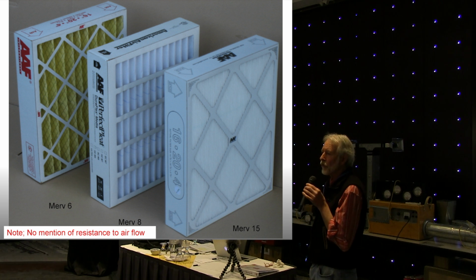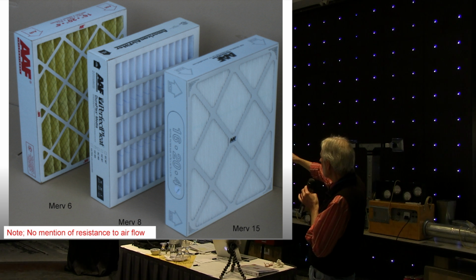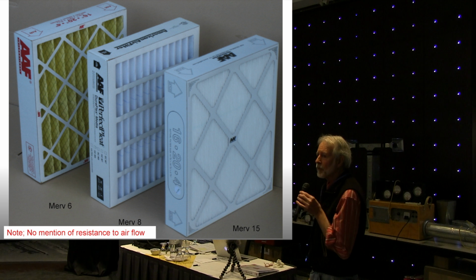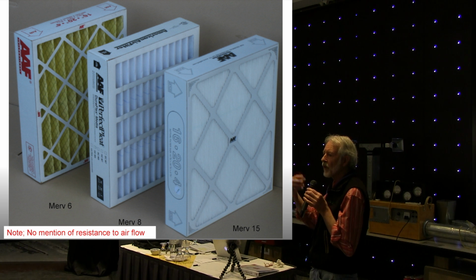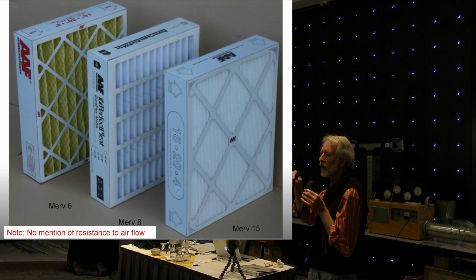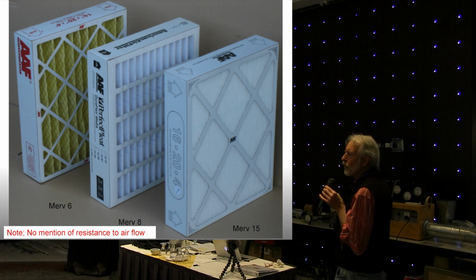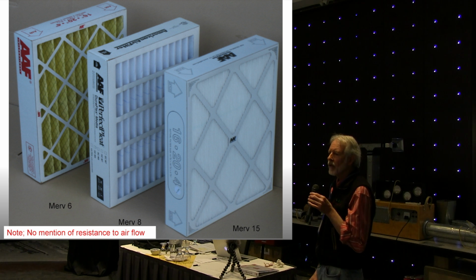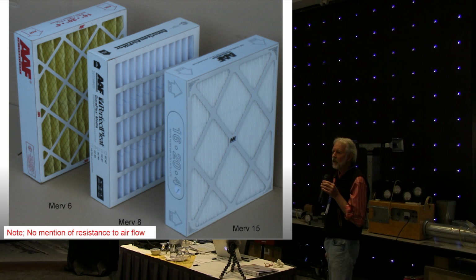But now we can put in filters that are reasonably economic, basically $10, $50, $120, $30. We can put in good filters right now that actually improve our respiratory systems by taking out the particles which we would have otherwise inhaled. The stuff that's so small it doesn't settle, the stuff that stays in the air until we breathe it. The problem today is these are being sold on a MERV basis only, with zero concern for the restriction that they impose in the heating system.